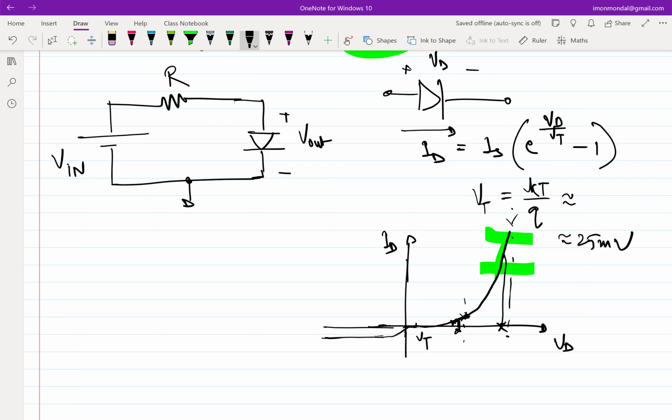Use KVL, right? You can use either KVL or KCL, it's a single loop, it doesn't matter. But essentially, to solve any network, you require three things. You have to apply KVL, KCL, and you also need the current-voltage relationship of all elements in the network, right? All three things put together, you will get a set of equations to solve. So that's what we will be doing.